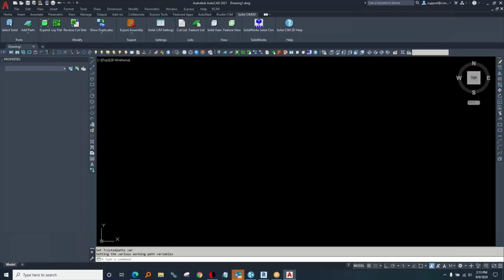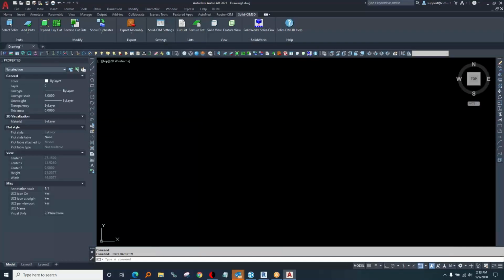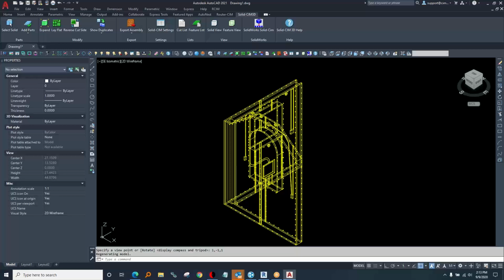What happens next is it transfers the model into CAD. And there it'll turn each one of these parts into individual drawings with geometry on different layers, and then that layer will indicate what type of toolpath to make. This process takes just a second or so.